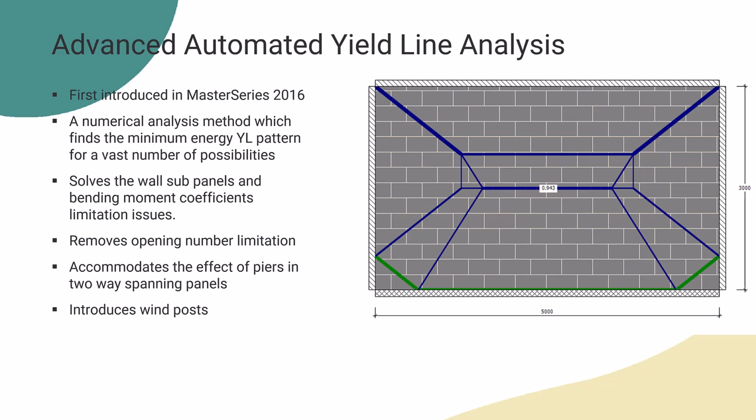So the advanced yield line analysis has the opportunity to look for other patterns, and it's maybe found something that's ever so slightly less than the alternative pattern with yield lines forming at these corners, because we've got a fixity along the bottom. So there's a very, very minimal difference between the optimum yield line and what engineers would assume to be the best fit for simplicity. I don't think designers should be too worried about that.